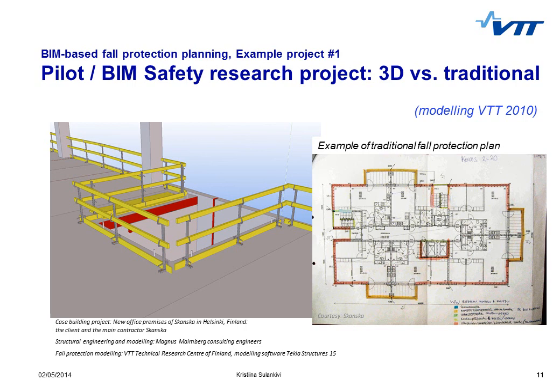And on the left you can see an example of a detailed BIM-based fall protection plan made by VTT on behalf of a research project, using the project's structural model as a basis and Tekla Structures as the tool for safety modeling. This case project was an ongoing construction project and modeling was based on the information gotten from the site manager concerning fall prevention solutions they aimed to use in this project.